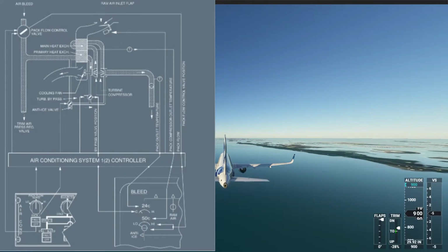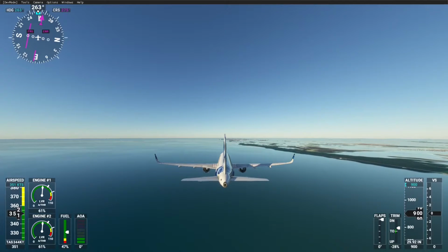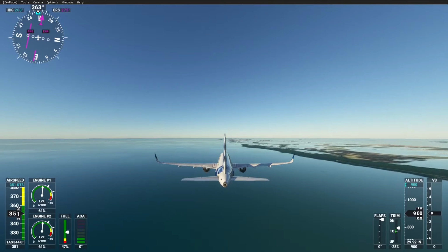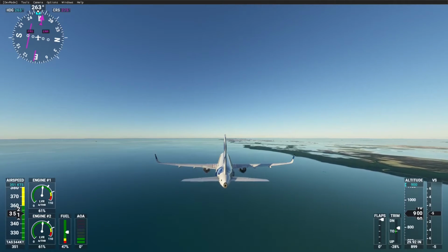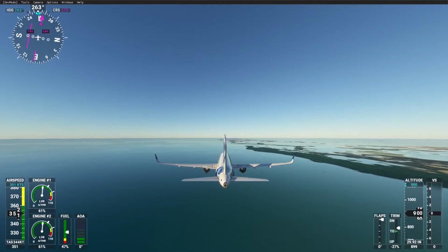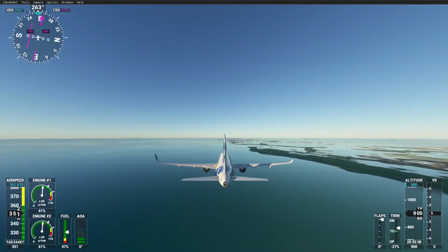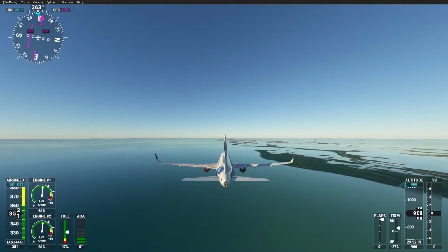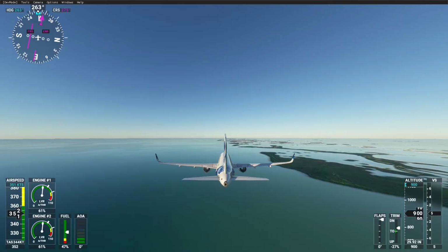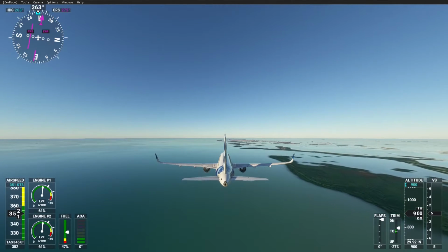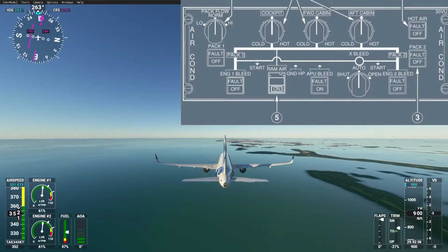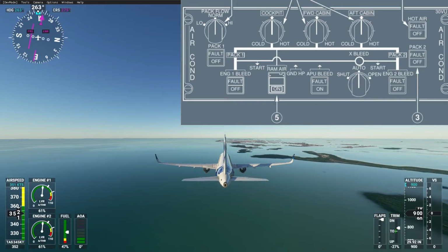They will, however, shut this ram air inlet that provides that cooling air during takeoff and landing, this being from takeoff as soon as you set the power to the gear being uncompressed, and during landing it's from the moment the gear is compressed to 20 seconds after you've reached 70 knots. But effectively, what do you need to know here? You need to know that that ram air inlet should be shut on takeoff and landing. Either way, at my operation we generally take off without the packs on anyway, so it won't have that much of an effect, and it only really has the effect after landing.